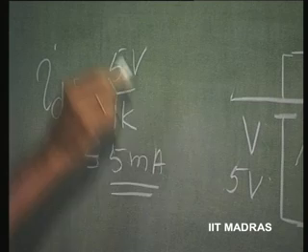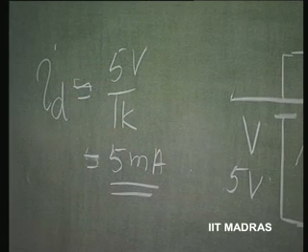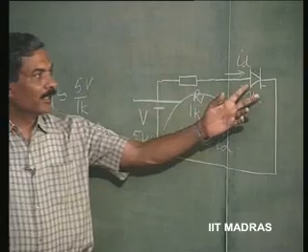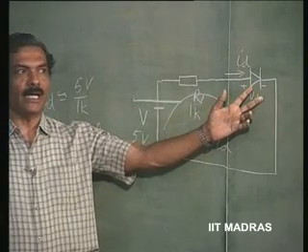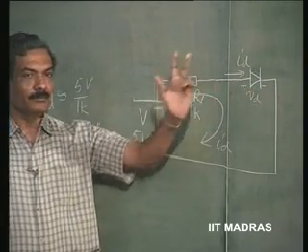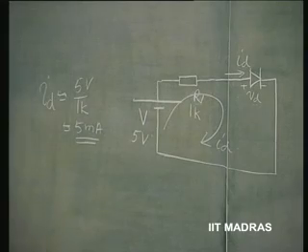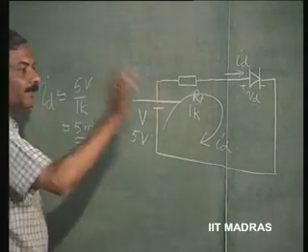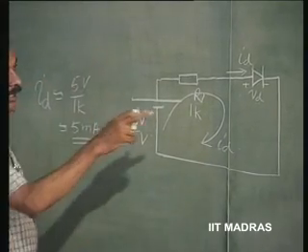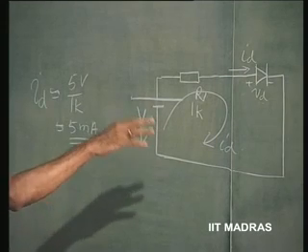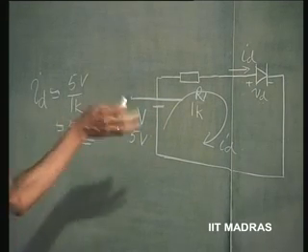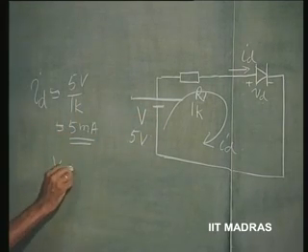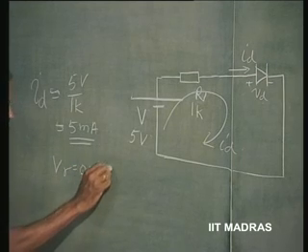This is the first order of approximation in a diode circuit which is forward biased. What it says is that the diode drop is that of the ideal diode, and therefore it is 0. Then, if I say that it is a semiconductor diode, it immediately comes to our mind that the drop is between 0.5 to 0.7. So, let us assume it as 0.6 volts. So, V gamma is equal to 0.6 volts.